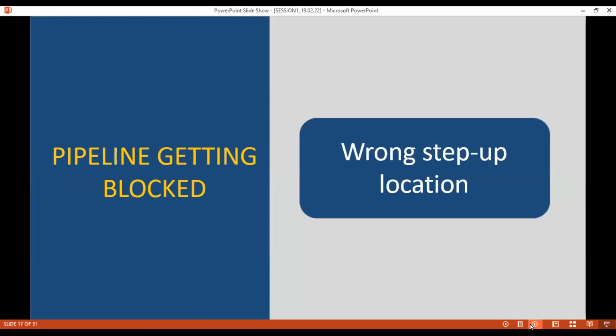The second important matter is pipeline getting blocked, but this may not be because of insufficient air, but because of the wrong step-up location. Sometimes certain system suppliers have given too many step-ups. In a 1 kilometer line, they have given 3 different pipe diameters. So that is 2 step-ups. Why are the step-ups given? Step-up means increase in pipe diameter. They are given to reduce the pressure drop in the line.